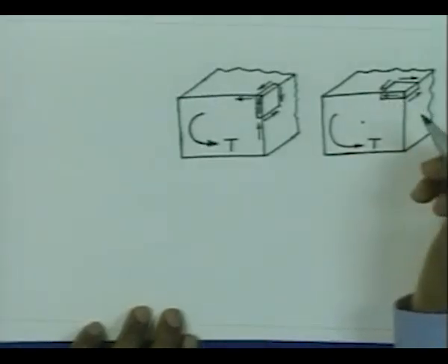So, corner stresses: the same type of argument can also be considered for the triangular cross section. You will find that, for that matter, any corner is going to be free of any shear stress in a torsion problem. So, note that the stress at the furthest point, which is the corner, is 0.